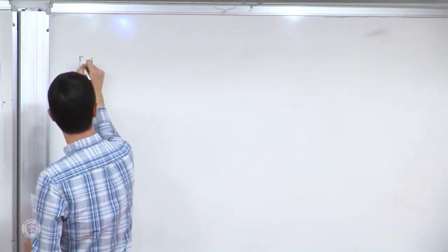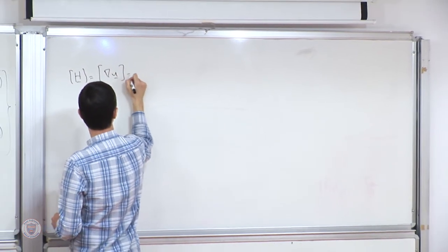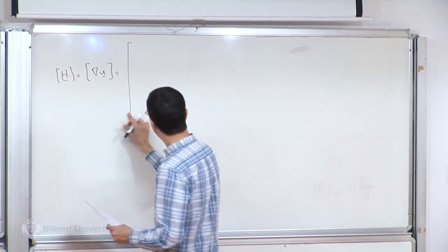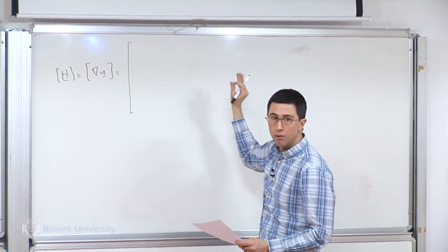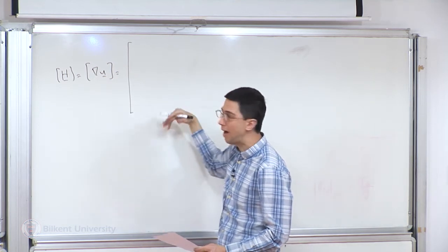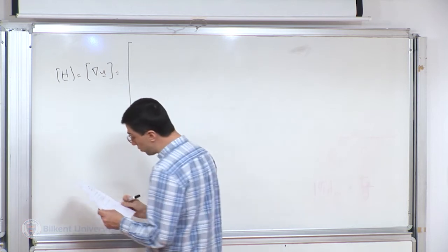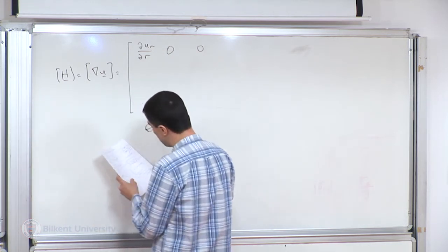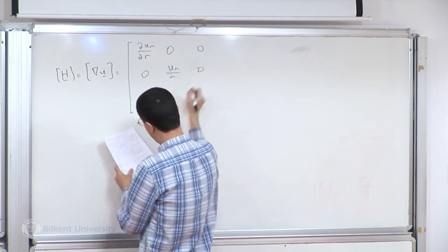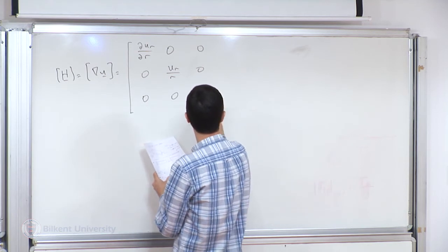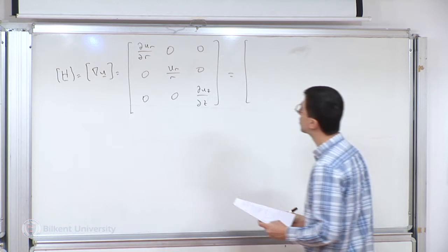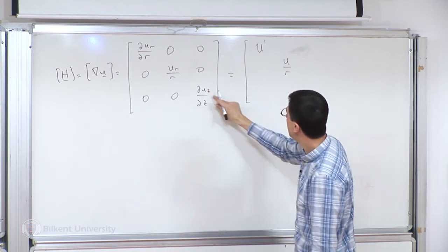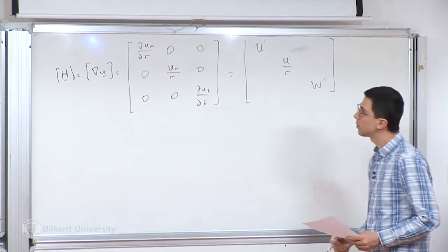And then I go ahead and calculate first the displacement gradient. As I mentioned last time, I'm going to always remind you from now on only the particular parts that survive based on our simplification. So we've written the full gradient last time. This time, the only thing that remains, first I will write what remains, and then I will use our notation to plug it into that form. So what remains is this in the gradient in polar coordinates. So u_r,r is simply U prime. And then we have U over r. And then this is simply W prime. Okay?